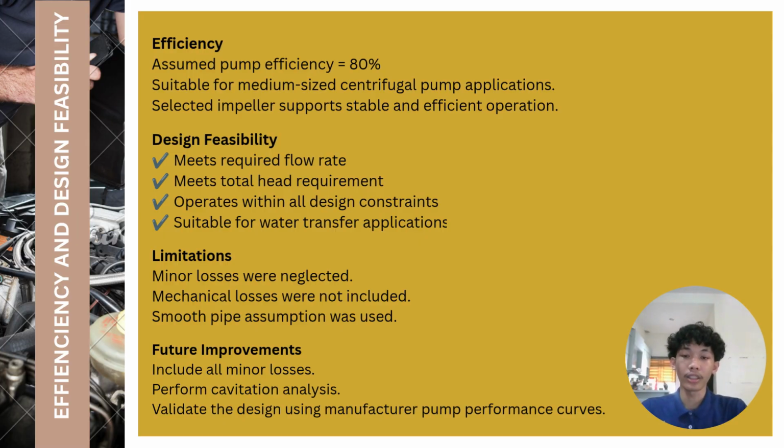several simplifying assumptions were made during the preliminary design stage. Minor head loss, mechanical loss, and pipe roughness were neglected to simplify the analysis. For future improvement, the design can be enhanced by including all minor loss, performing a cavitation analysis, and validating the result using manufacturer pump performance curve.